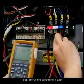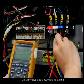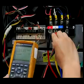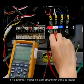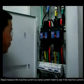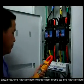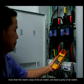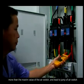Step 1. Check if the input power supply is stable and whether the voltage drop is obvious while starting. If it is abnormal, a stable power supply must be provided. Step 2. Measure the machine current with a clamp current meter to see if the machine current is more than the maximum value of the air switch, which leads to the air switch jumping.